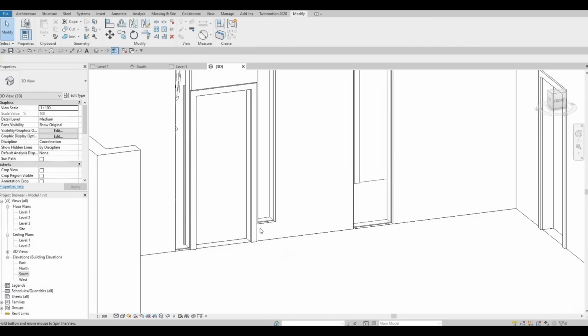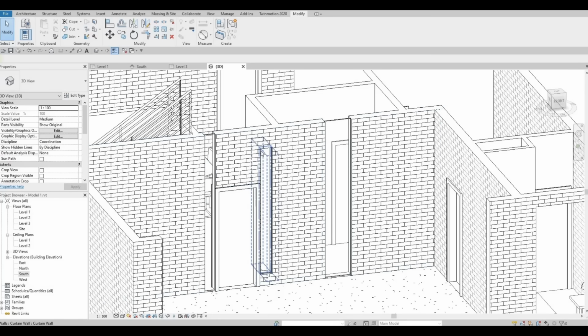And then after that, if you want to copy the same height as this, you could go to Modify or Align, AL, type in AL. So we want to copy the curtain wall height like this, and then below like that. So that one's copied.